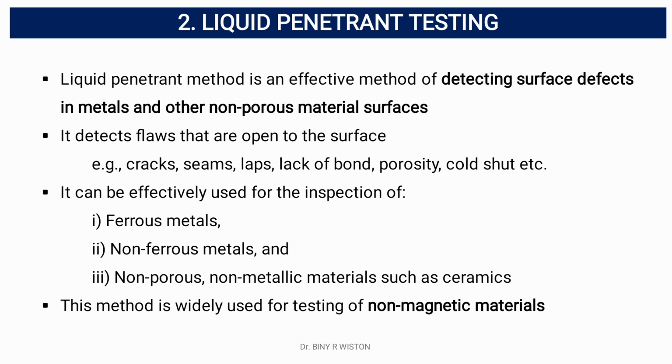LPT detects flaws that are open to the surface like cracks, seams, laps, lack of bond, porosity and cold shut, etc. It is very effective in inspection of ferrous metals, non-ferrous metals, non-porous, non-metallic materials like ceramics, etc. This method is widely used for testing of non-magnetic materials.